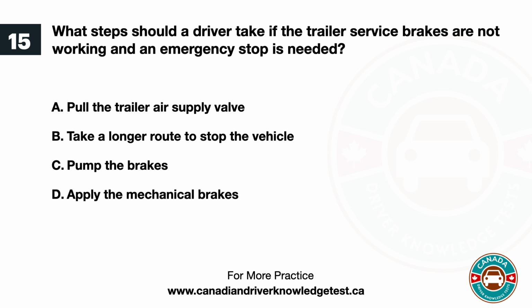Question 15. What steps should a driver take if the trailer service brakes are not working and an emergency stop is needed? A. Pull the trailer air supply valve. B. Take a longer route to stop the vehicle. C. Pump the brakes. D. Apply the mechanical brakes. The answer is A. Pull the trailer air supply valve.